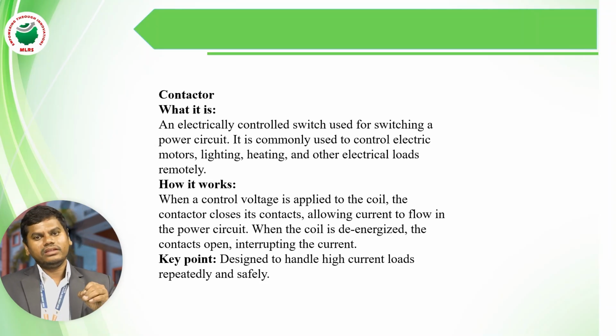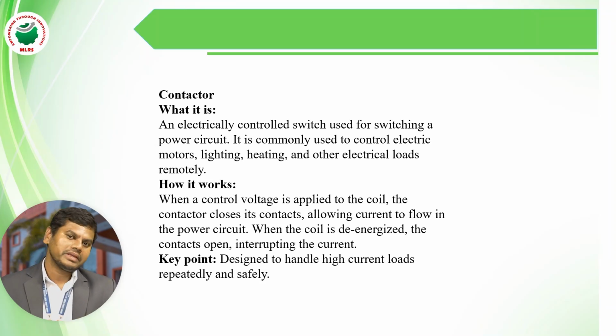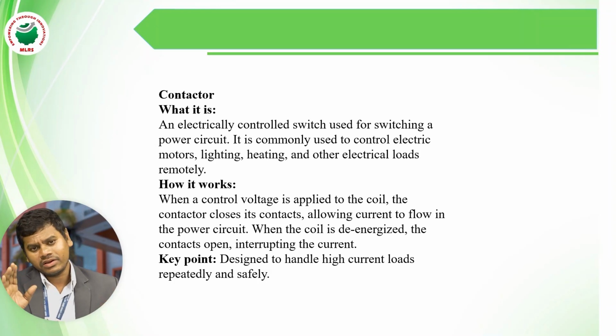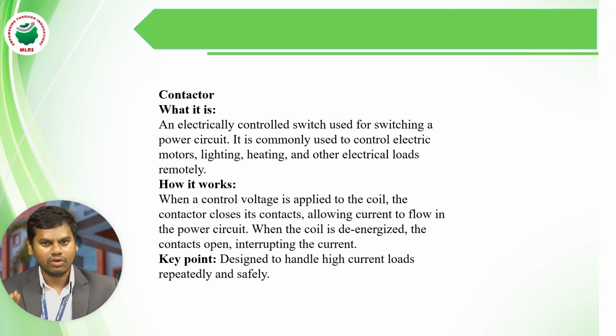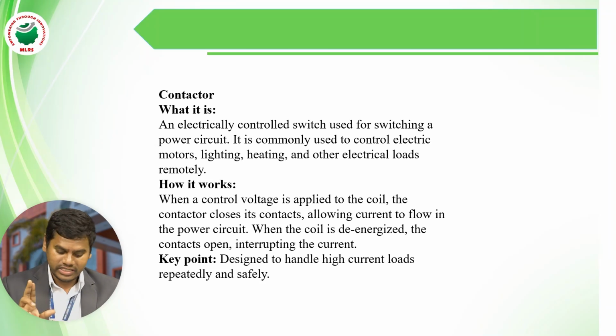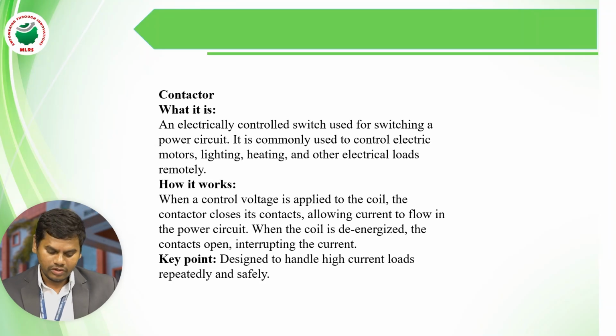This is the working condition. So what is the working condition? When a control voltage is applied to the coil, that is the first thing. The contactor closes its contacts, allowing current to flow in the power circuit. When the coil is de-energized, the contacts open, interrupting the current. This is the working condition of the contactor.